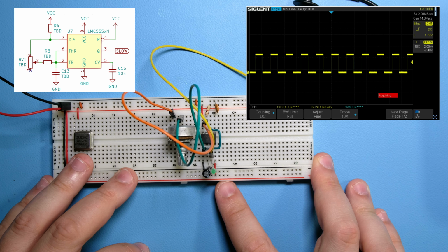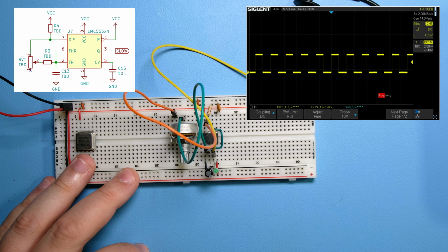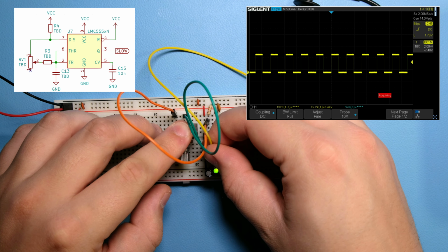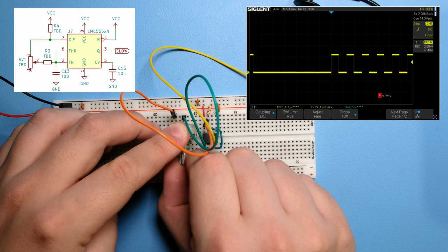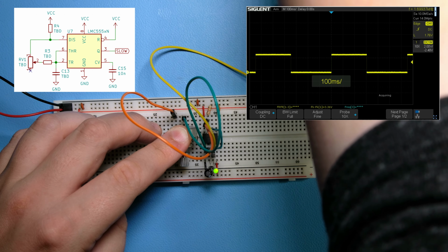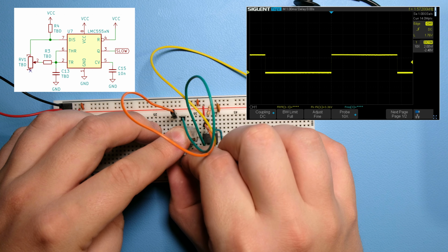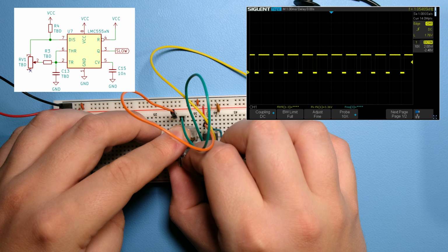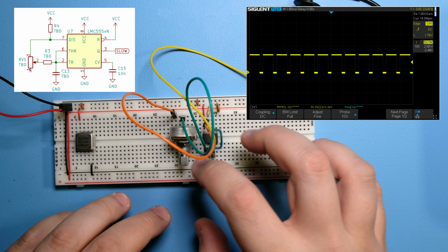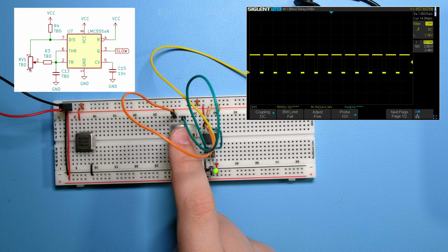So this seems to be a pretty good low frequency for the clock so that we can see what happens on the board. Remember that we're going to also divide it by 2, so it's going to be twice as slow. And then if I go up, we go higher than 1 kilohertz, which is a bit much. So I'm going to add a series resistor with a potentiometer, because when this goes to 0, then the frequency goes to a very high value.